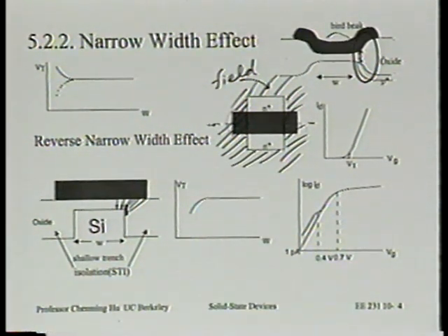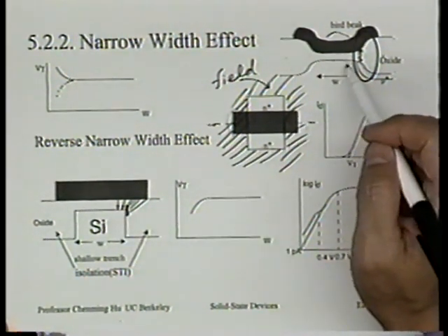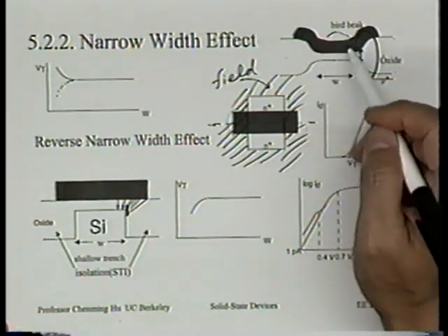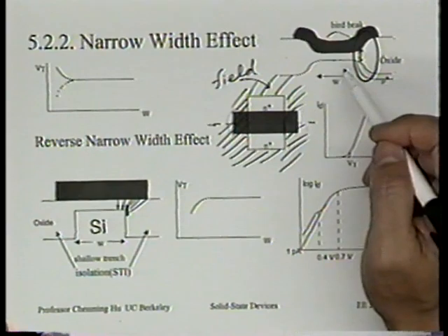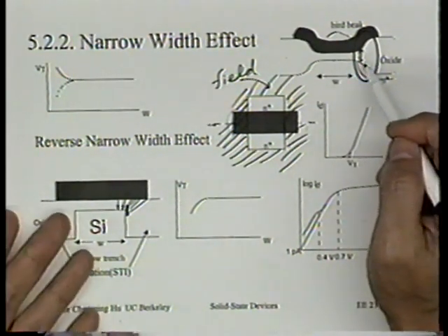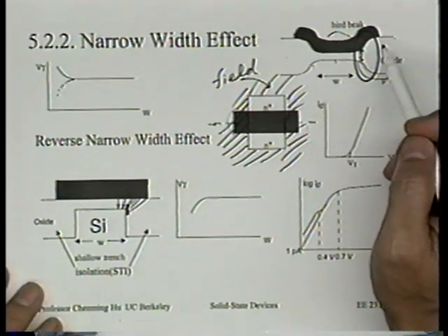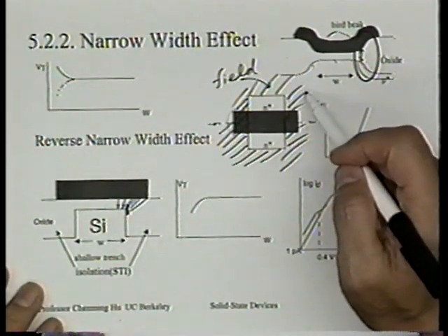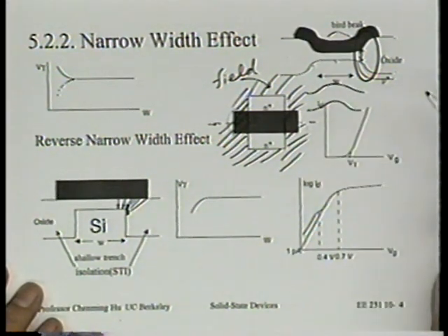And the best way to visualize that, if this helps, it's great. If it confuses, then just ignore what I'm saying. Here is why you cannot just think of the transistor as being made of three transistors, one VT, one lower VT, two larger VT. If that were the case, then you would say, gee, VT is determined by the lowest of the three VT values. You cannot really think that way, because you have to think about this concept of the energy band diagram as what determines the VT again. Right?